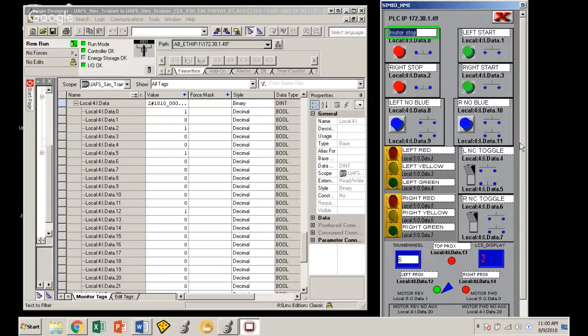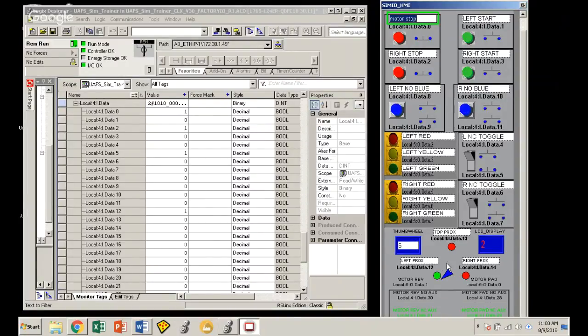You also have a motor simulator. So you have a forward reverse motor with 3 prox indicators that represent the position of the motor. There is actually a feedback signal, normally open and normally closed, from the motor contactor with a slight delay. So it represents the delay of the mechanical action of the contactor closing, just like you would have in a real PLC controlled contactor. So if we want to go here, we can see that motor reverse is on card 5.